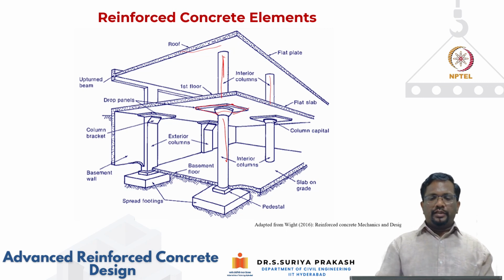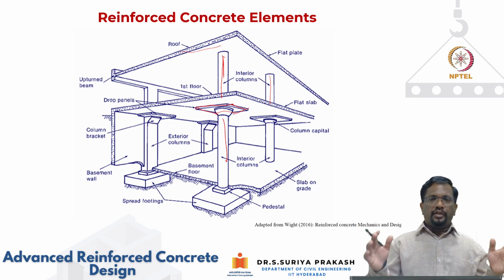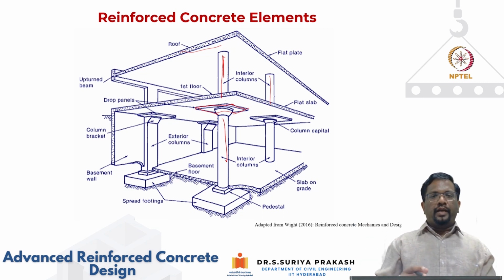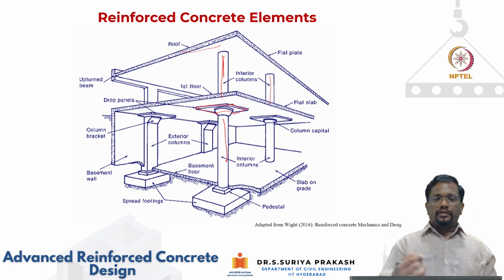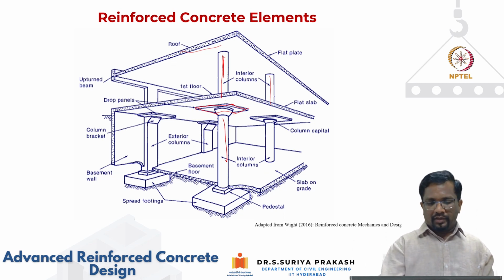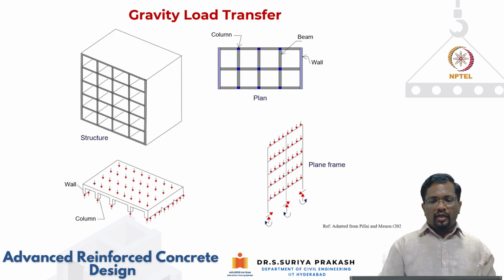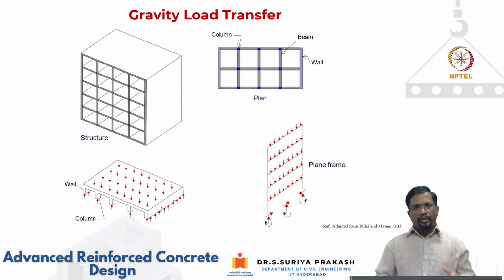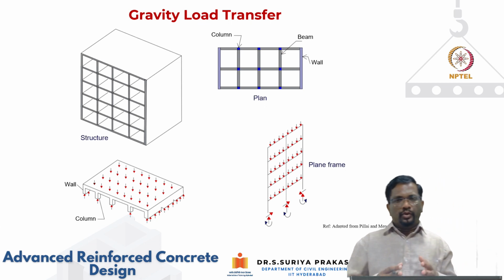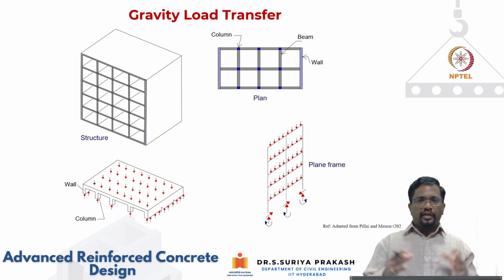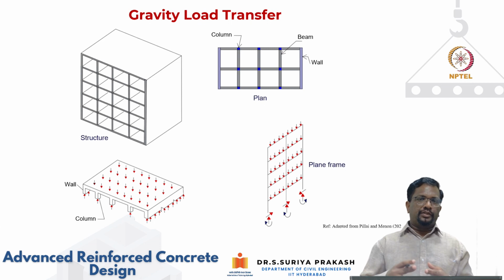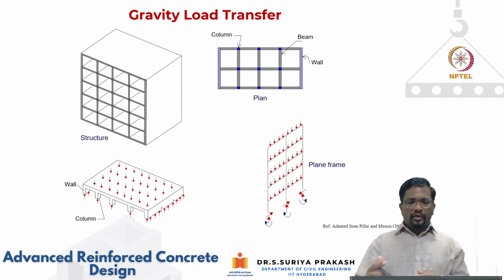So that is the reason in modern day construction usually these flat plates are post-tensioned. They're called post-tension slabs, and if you design it properly with an adequate lateral load resisting system, in fact, this would be an attractive option for spanning the slab. Okay, so for buildings, we looked at how certain structural elements are arranged to transfer the load.